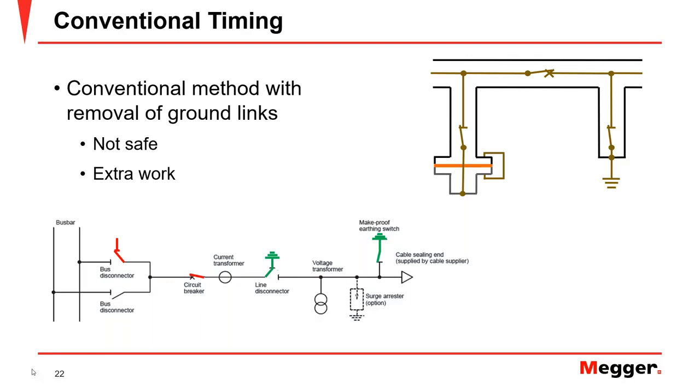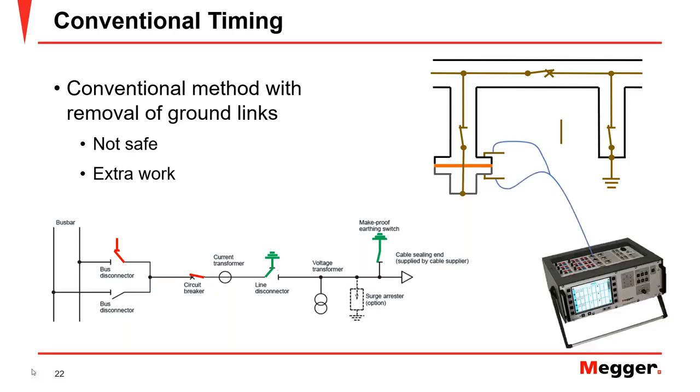So we have to remove the shunt. Once that shunt is removed, the circuit breaker is in open position. The housing of the insulated earth switch ends up in a floating state, and that will be exposed to capacitive coupling from nearby lines. When you're doing maintenance testing, of course, if you are performing commissioning tests, you're free to use this method. You remove the shunt, connect the circuit breaker analyzer, and test using the traditional methods.